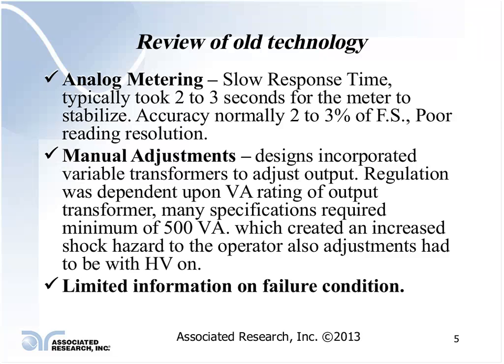What problems does this create? Using a high current capacity instrument creates a little bit more of a hazard to the operator. If you think about it, if you've got a 5,000 volt, 500 VA rated tester, that instrument is capable of producing 100 milliamps of output current under a full load condition.